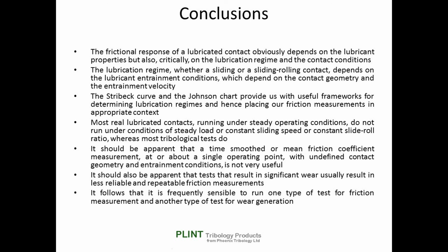Although friction measurement under boundary lubrication provides a useful indication of wear transitions, it is usually not much help if we are concerned with frictional losses in most lubricated sliding or sliding rolling contacts. Most real lubricated contacts running under steady operating conditions do not run under conditions of steady load or constant sliding speed or constant slide roll ratio. Most tribological tests do.